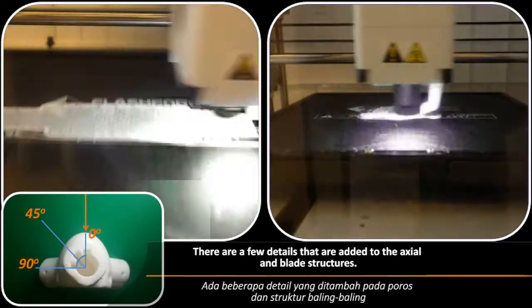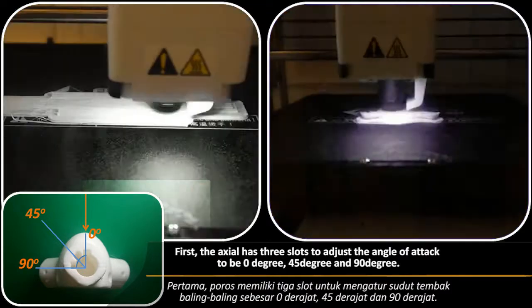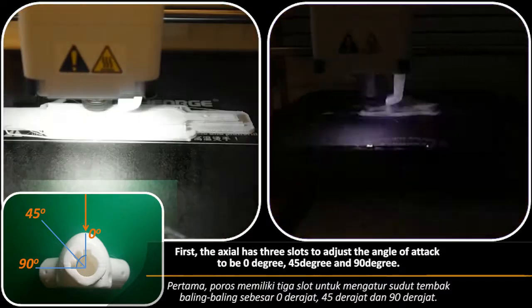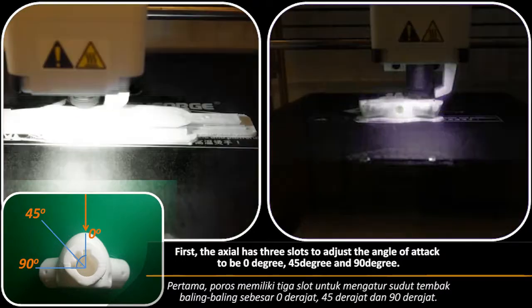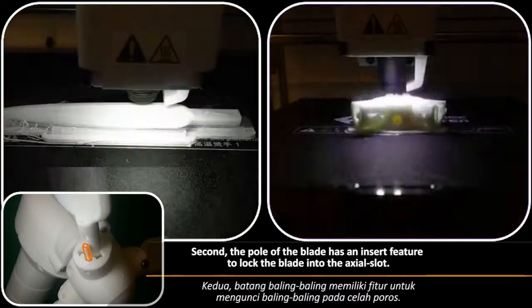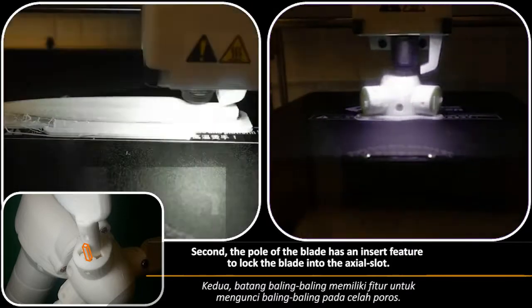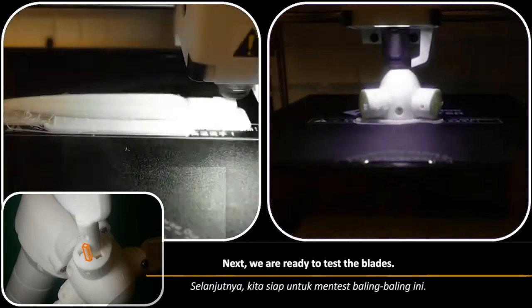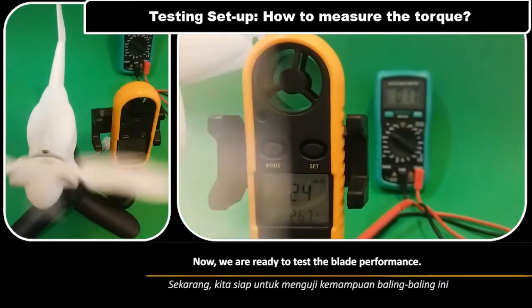There are a few details that are added to the axial and blade structures. First, the axial has 3 slots to adjust the angle of attack to be 0 degrees, 45 degrees, and 90 degrees. Second, the pole of the blade has an insert feature to lock the blade into the axial slot. Next, we are ready to test the blade's performance.